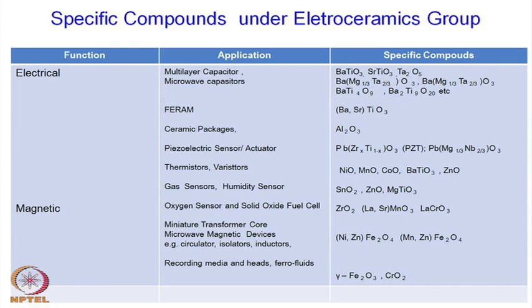All the silicon microchips have to be covered with some kind of a cover, and it should be isolated from the environment because it is very sensitive. Not only that, but there is a need for electronic connectivity between the microchip and the outside circuit. So, the ceramic package provides that particular